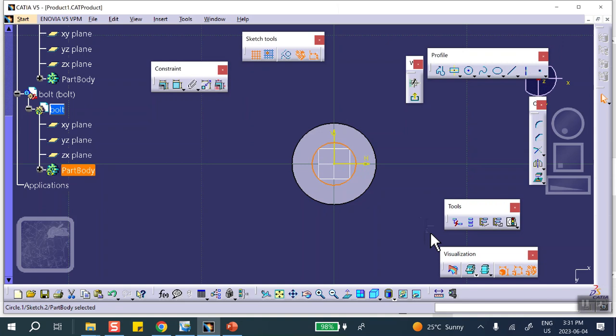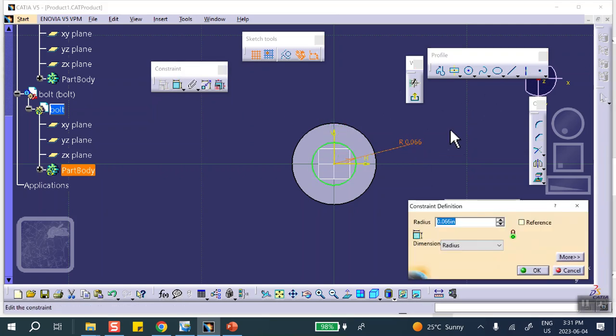The radius of that shank is the same as the radius of the bolt. So the hole. Sorry, the hole. So I'm going to make it exactly the same radius, but in reality, remember there is a clearance between them. But I'm going to make it 0.125. Oh no, not 0.125. What was the radius of that hole? It was 0.125. So it's that head that is wrong.